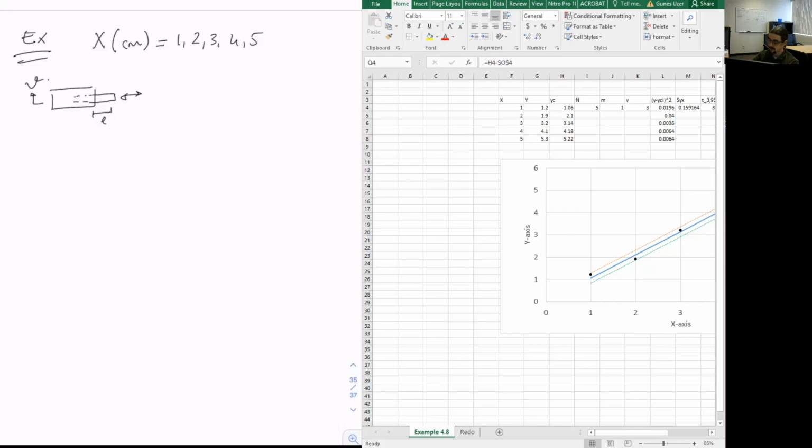So it's commonly used in instrument machine testing, so you can understand what the force displacement curve is, right? That displacement comes from an LVDT, and then you have probably a force sensor as well, and that will give you the force. So that will be two sensors. And then out of that, you get volts. Y output is in volts.